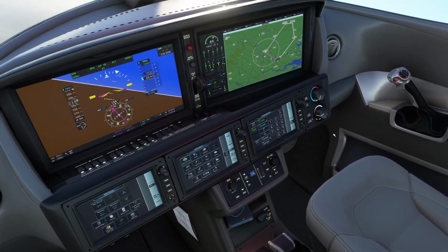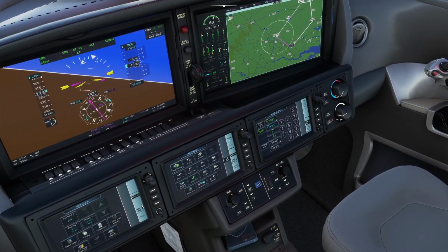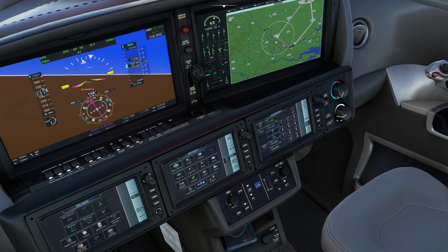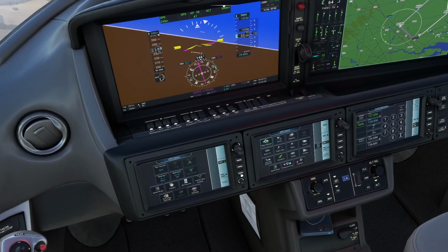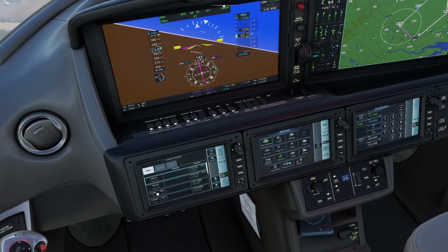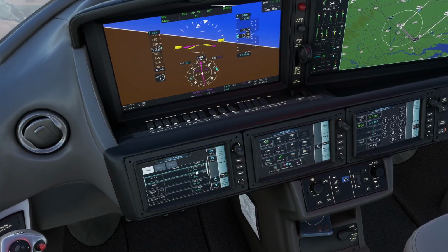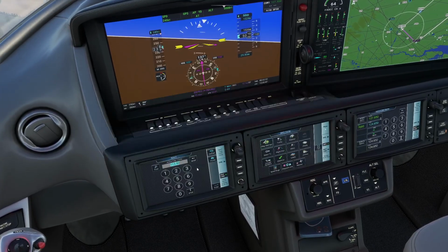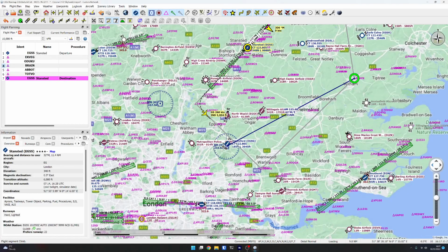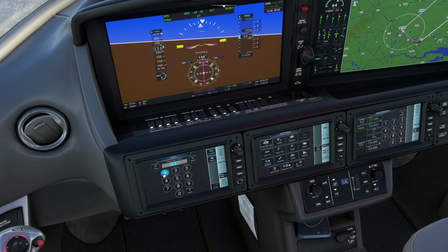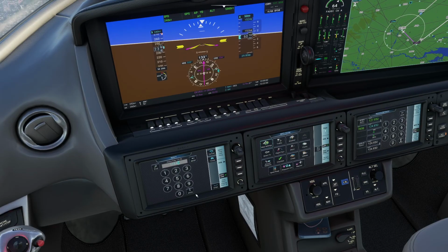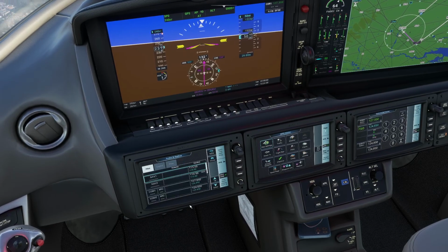And they are over here. You will notice they're on the navcom section, so you can get to them on all three screens. So if you go to navcom, you go to radios, nav 1 is here, so if we click on the frequency for nav 1, we could say 115.60. So 11560. Okay, and then we can press transfer to make it the active frequency immediately.